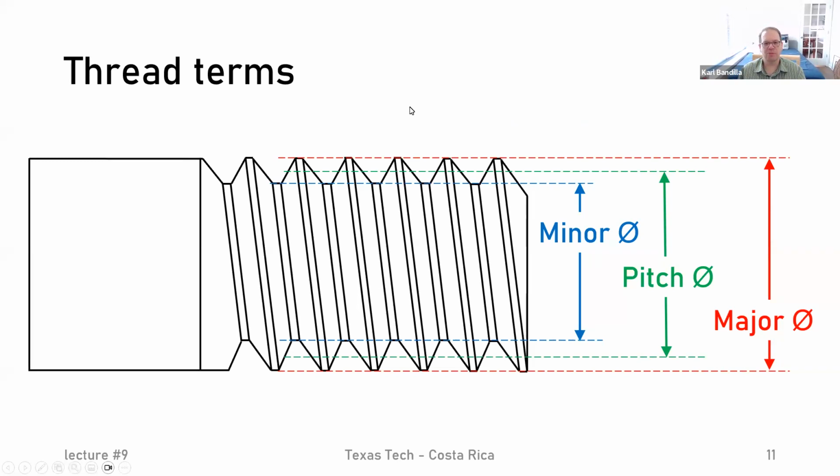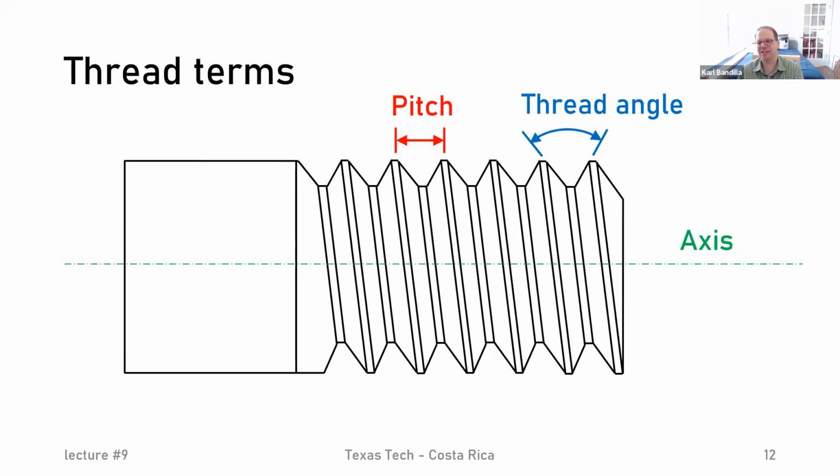Now, what is the pitch? Well, if you play soccer, then you know what the pitch is. That's the field that you play on, but of course, that's not what it is here. The pitch here is the distance between two consecutive threads, right? So if I'm standing on my little screw, like a little ant, and I start walking along this crest, I'm walking all the way around. And once I come back up, I'll be on the next one, right? It's hard to see, because we always see the front, but we're going down here, then coming back until we come back to the front, right? So this distance is what we call pitch. Pitch is, of course, measured as a length, right?